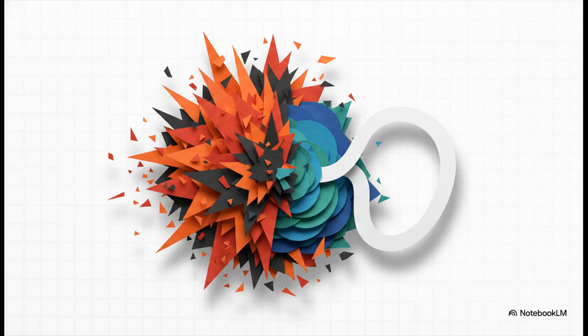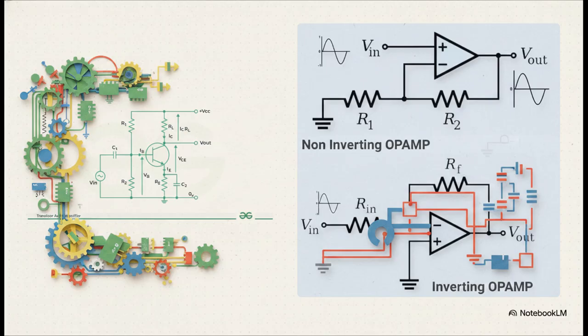All it means is you feed a tiny little bit of the output signal back to the input. And when you do that, something amazing happens. The circuit's performance suddenly doesn't depend on the op-amp's internal chaos anymore. It only depends on the stable, precise components you connect to the outside of it. And this slide just says it all, doesn't it?